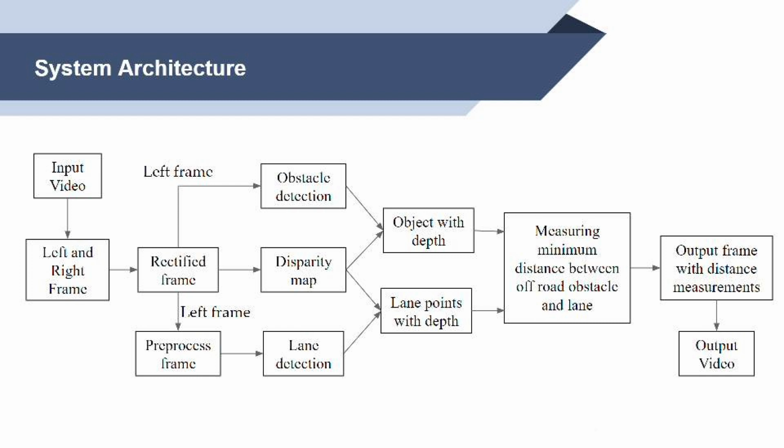Stereo vision. We utilize stereo vision as it allows for more robust distance calculation. The input video frame consists of left and right frames. Firstly, we split the frame into its left and right components. Next, we rectify both frames to eliminate lens distortion and align objects in the vertical direction using the stereo calibration matrix.